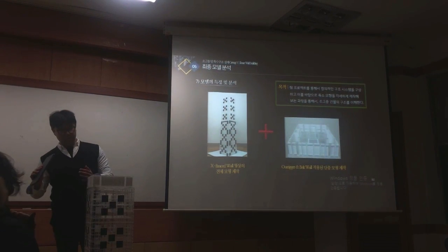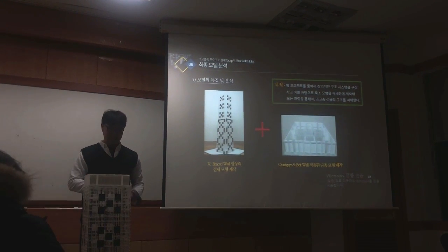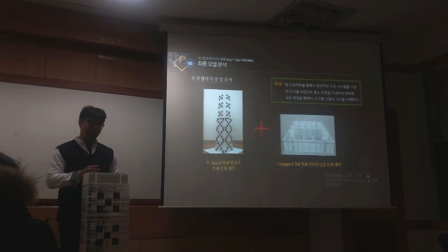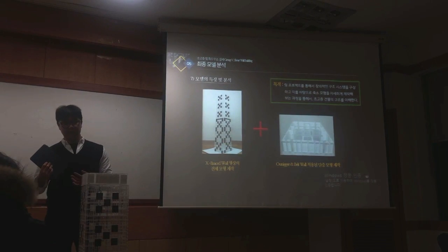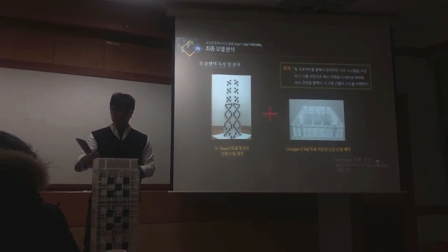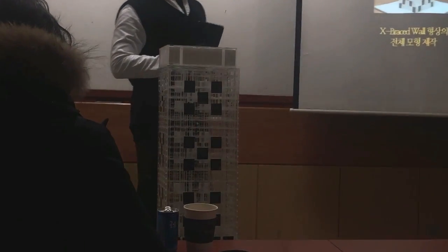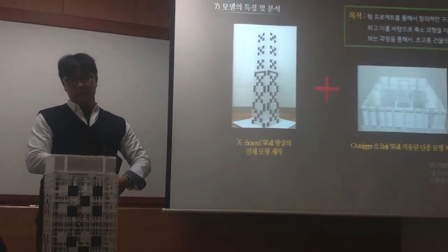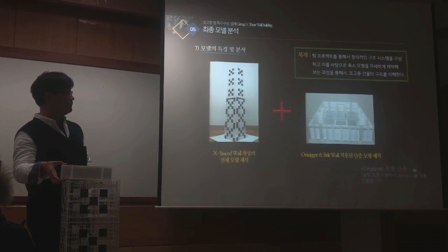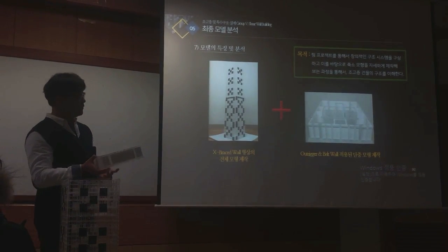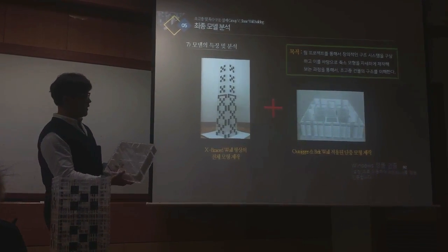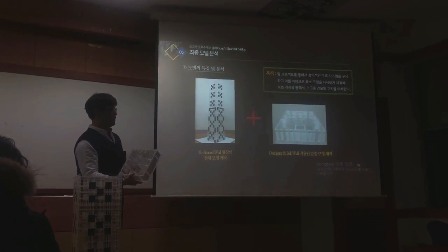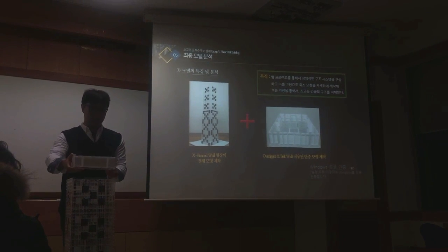But the X-shaped brace, we got to express that. So inevitably, we put some black stickers outside the walls, so you can know that it's an X-shaped brace wall. And this is a small version of our 33 floors. So it has used outrigger and belt wall system, and this is our model.